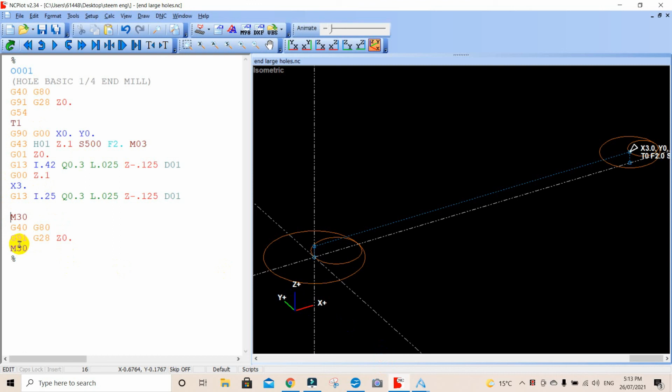So if you don't want to see it while you're doing it, you can leave that there and of course it will just leave that bit out. And when you finish the program you can just take that little space out. You can leave a space there, the CNC will just skip over it. But that essentially will machine those 2 pockets and machine them basically to chips. It'll just go to nothing, won't leave a biscuit in the middle.